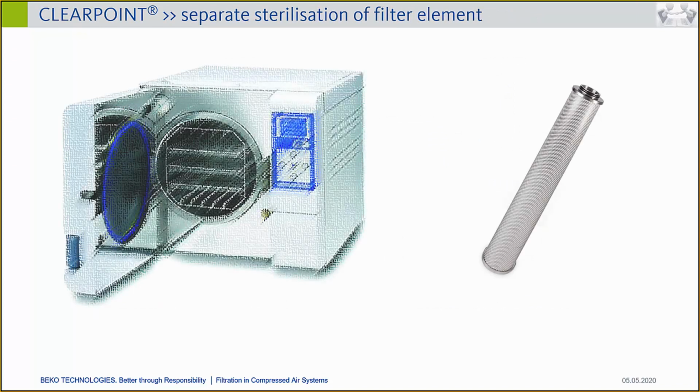Another option is that the sterilization can be done in a so-called autoclave, but for that purpose the filter element needs to be taken away from the filter housing and put into the autoclave for the sterilization process. And then again, the filter element needs to be placed back again into the sterile filter housing.